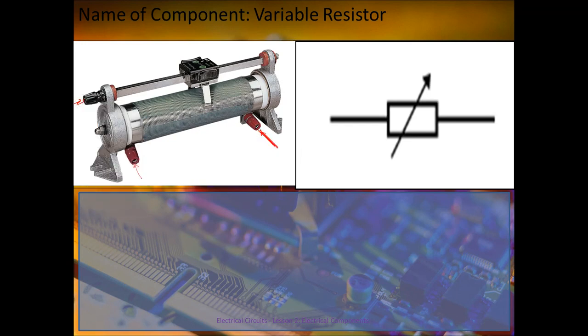And the way that these work is that we've got a nice low resistance bar across the top, so low ohms, and then we have a high resistance coil along the bottom. And we can choose when the current swaps from the bar to the coil. So the more bar it goes through, the easier the journey and the lower the resistance.